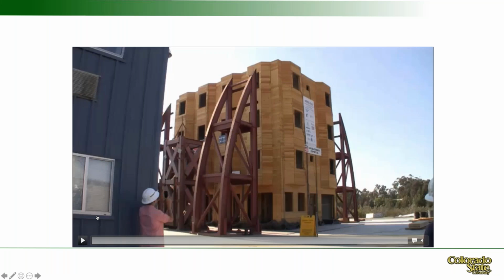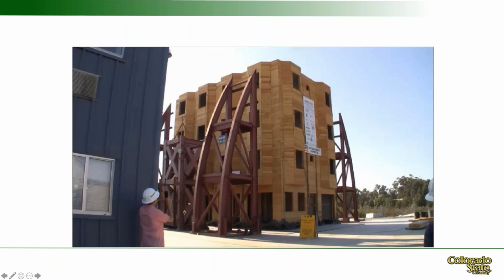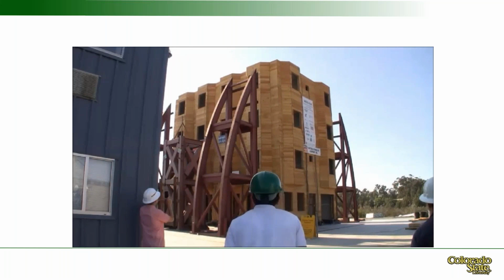Okay, so this is just a quick video of that, and to show you, now this is actually 100%, this is an MCE level Loma Prieta scaling. And so what you'll notice is it doesn't actually look like much because the building does so well. But you can see a couple of higher modes in there, and that's not unexpected.